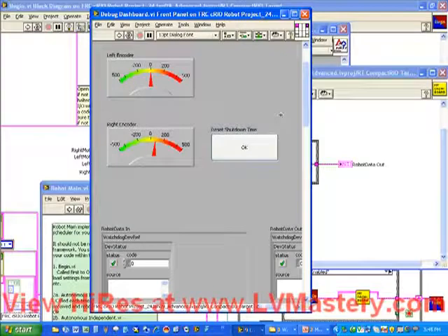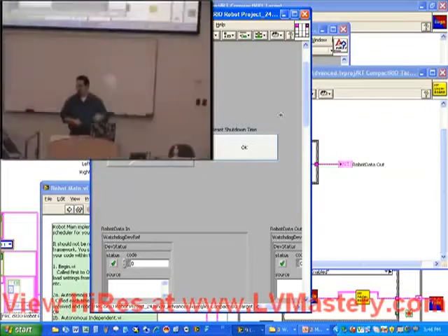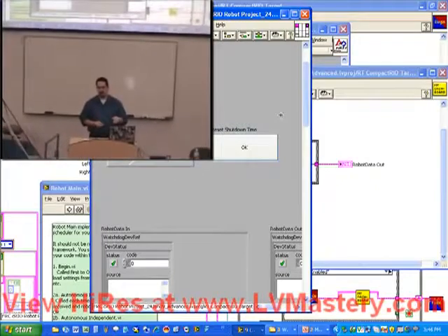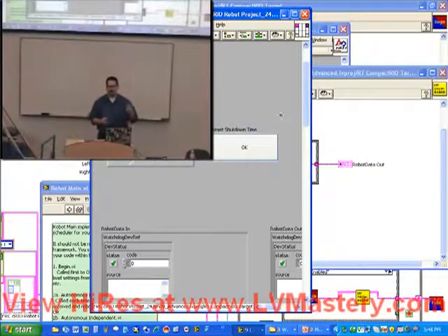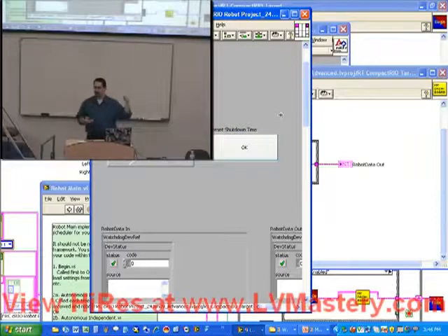button on your TV, you push it once, the TV turns on, it stays on. You push it again, the TV turns off. From the point of view of LabVIEW, that's called a switch. That means when you push it, it stays where it was. The other type of button is called a latch. And that's where it's more like the keys on your keyboard. You push the J key, you let go, the J key comes back up. We want a button that behaves like that. We want a button that as soon as we push it, as soon as it's red, it goes back false.